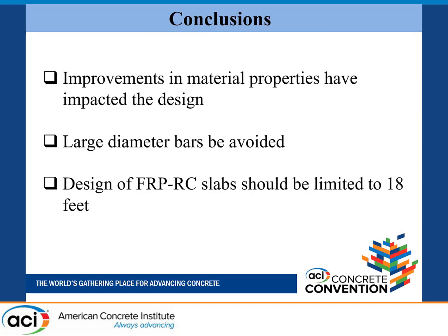And design of FRP reinforced concrete slabs should be limited to 18 feet, because if you go beyond 18 feet, your thickness will be very, very large. So to avoid that, it's advisable to limit your design to 18 feet.